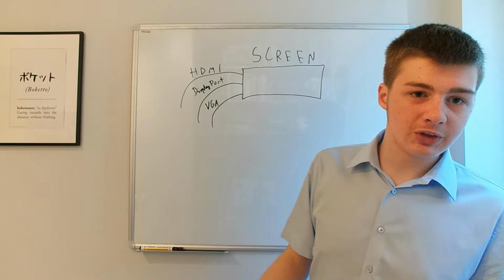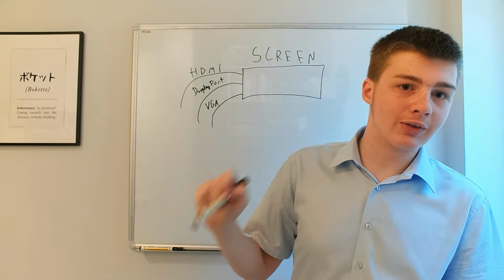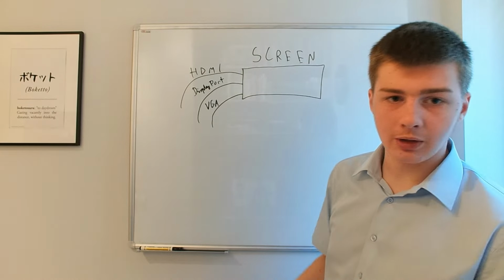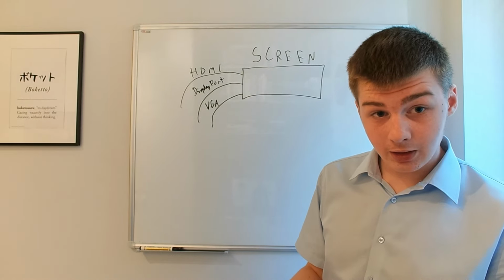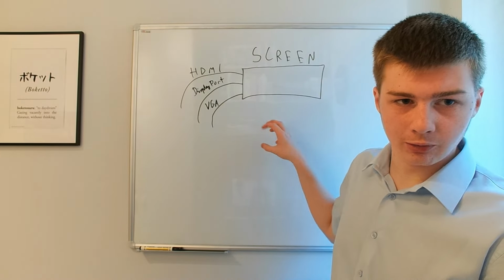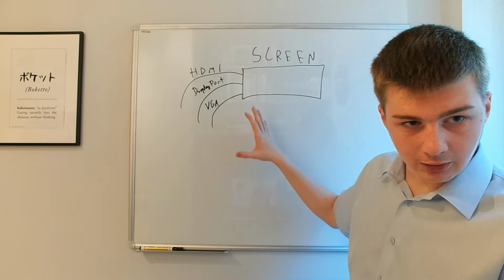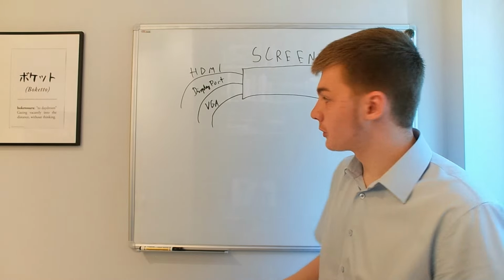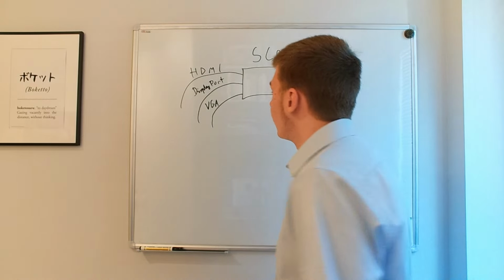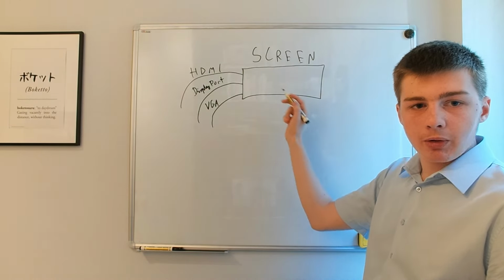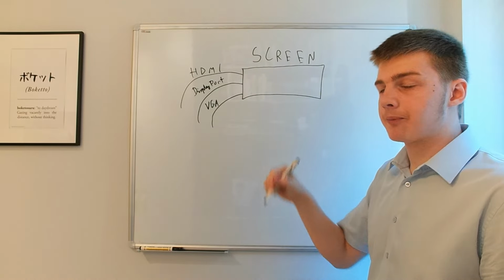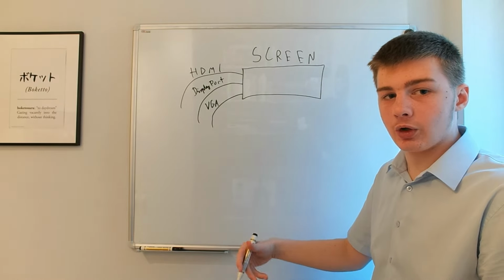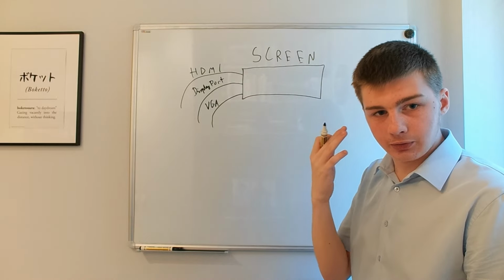According to those timings, the screen can then identify the mode, then use other electrical information, which is actually the analog information, where there are a lot of resistors to manipulate it and get it to the correct RGB values, which are stored as analog electrical parameters. The screen can understand the mode based on the timings, and then it can adapt and display those analog values in some way so that it is visible.